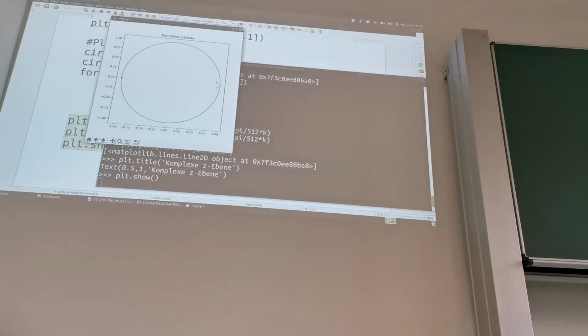So you can imagine you basically obtain the transfer function by going along the unit circle, starting here at 0. Here you get the largest output in this vicinity. Then you go on and on and on, and here you get the lowest output, which is 0 at this point. And this is then Nyquist. So at that point you would stop because we only have real values here. Make sense?